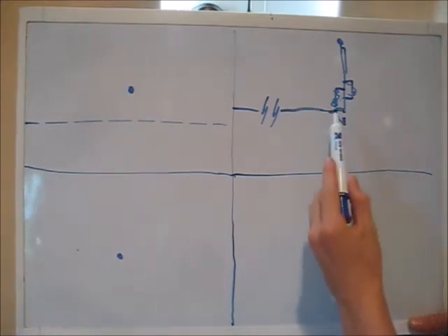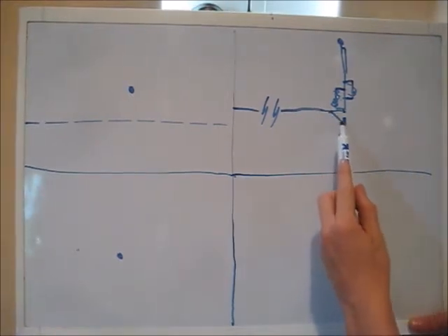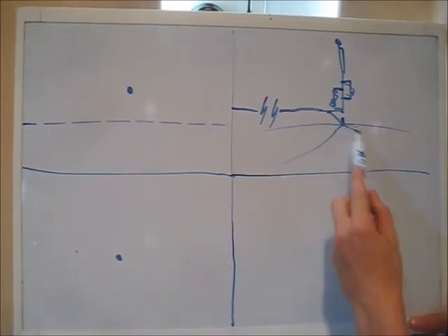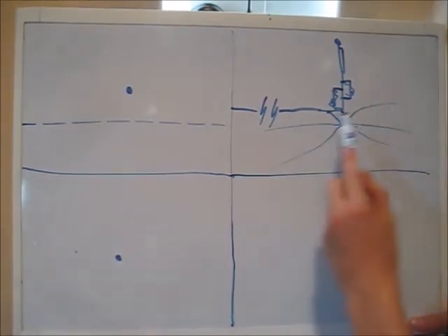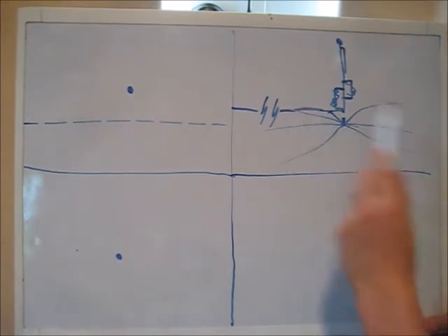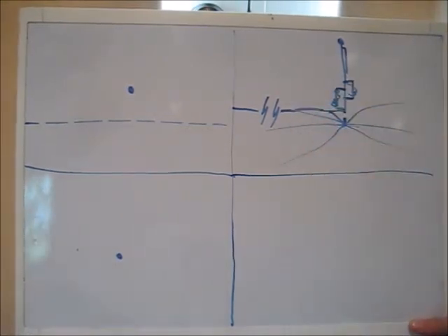Which every vertical needs is radials. Radials are just pieces of wire right below the surface of the ground, running out in all directions. And the more the better. And I'll get to that in a minute. But that's the basic operating theory of a vertical.